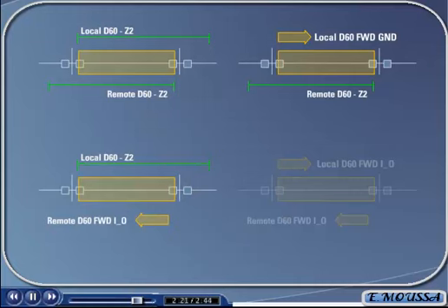In Diagram 3, the forward-flowing ground current of the remote relay and the Zone 2 picking up on the local relay is a clear indication that the fault is on the transmission line, and so both breakers will be tripped. Finally, in Diagram 4, the direction of ground current detected by both relays is flowing into the transmission line, which is again a clear indication that the transmission line is faulted, resulting in the tripping of both breakers.